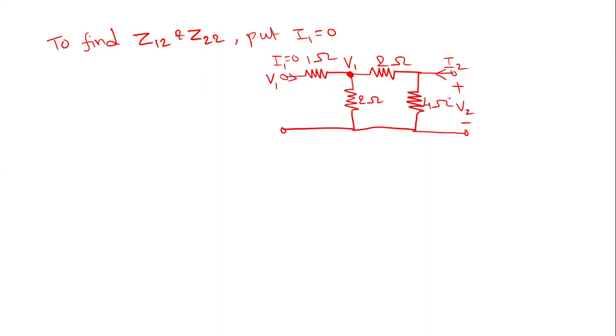Okay. Now, if you find the equivalent resistance at the output, what is R equivalent at output? This is open circuited, so there is no current flow. These 2 ohms and 2 ohms are connected in series, so 4 ohms parallel with 4 ohms. 4 parallel with 4 is 4 by 2, or in detail, this is 2 ohms.